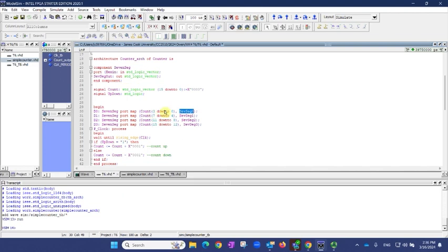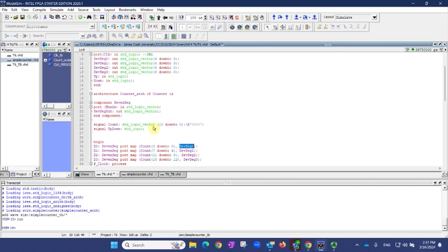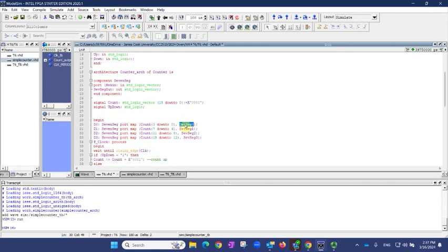It's called a positional port map because when you define or build your 7 segments, you declare this one first and then this one. So this signal will go to this position and this signal will connect with this part. You connect the least significant bits to the input of the 7 segments, and the 7 segment will output something. You connect it to the output port as 7 segment 0 you create here. You do it 4 times, so this full 7 segments output will be assigned proper numbers.